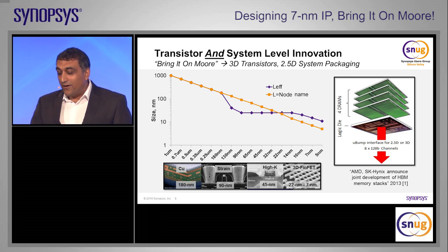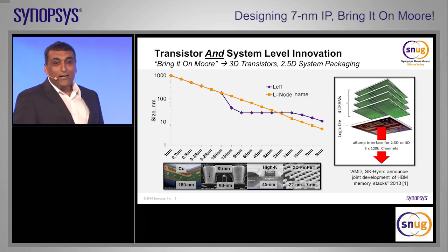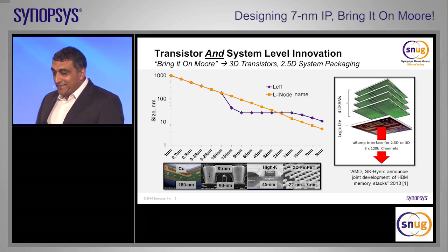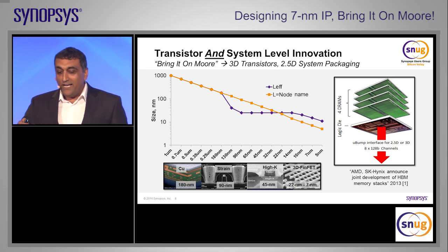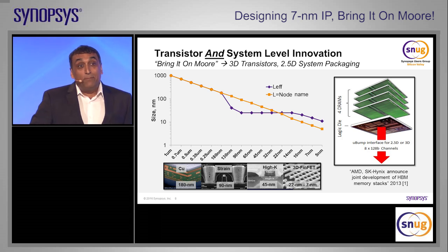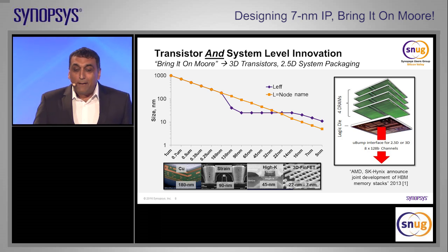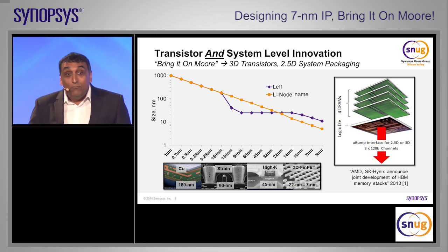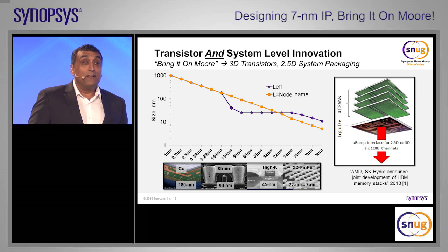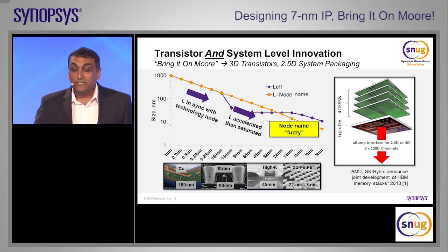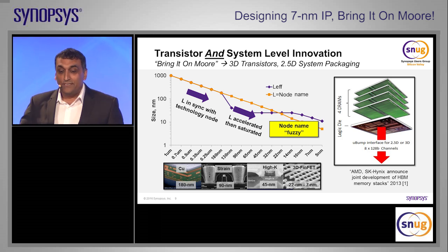There's something very interesting about this slide. If you look at the orange line and the purple line, they don't quite follow each other. Up until about 180 nanometers, if you were an engineer designing in 180 nanometers, that's what was actually being manufactured. That represented the effective channel length. And then something weird happened. The fabs started innovating more, right? They started introducing new materials. The L effective actually became smaller than the node name. L was in sync with the technology node. L accelerated, and then it started to saturate.